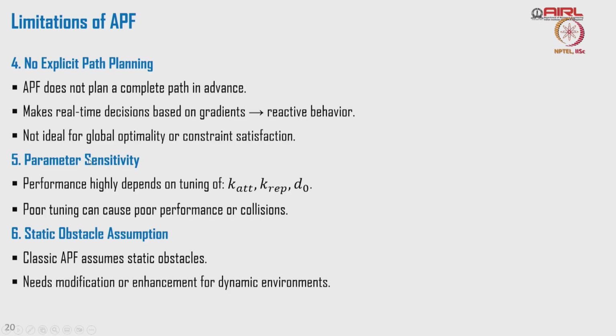It's also very sensitive to the parameters. The performance of APF highly depends on K attractive, K repulsive and D naught. These are the key parameters. They will influence time to reach and minimum distance with respect to the obstacle.